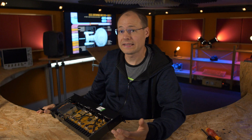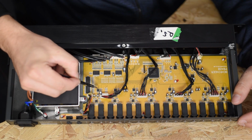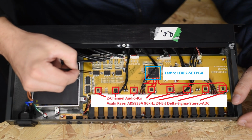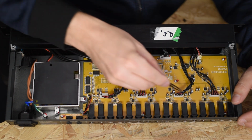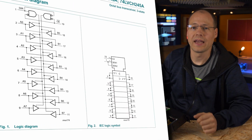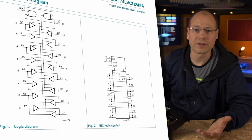To get a better overview, let's list the individual ICs and take a look at the basic connections. Directly at the jack connections, we find the analog-digital converters for the audio signal. These are connected here to an FPGA, which then passes the processed signals to 3 octal buffer ICs. These are then connected again to the 6 Cat5 connectors on the front. The many additional cables connect the input level selector switches and the LEDs. If we look at the datasheet of the octal buffer IC, we see that we have 8 inputs and 8 outputs. And here it seems that we are simply matching the levels of the FPGA to the levels of the output signals. So let's connect an oscilloscope to check the signals.